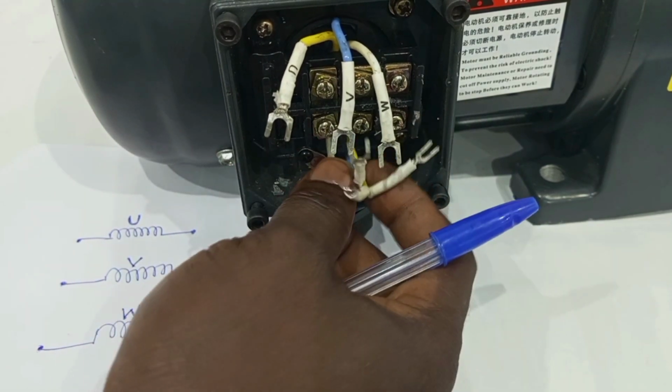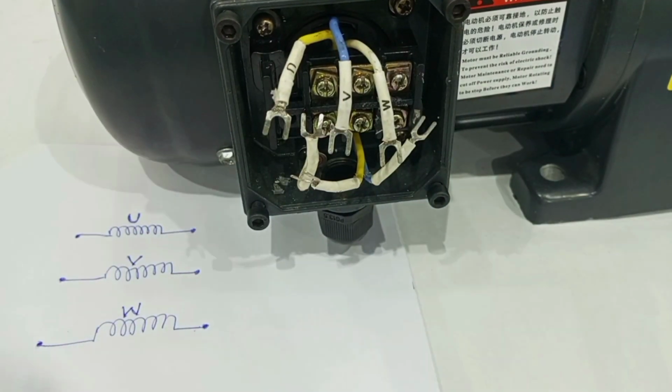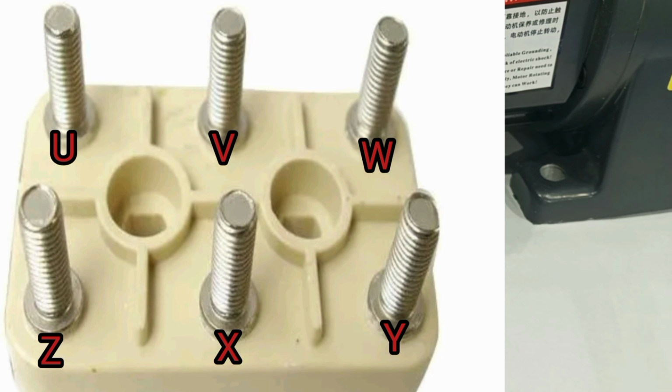Or you can take those at the down as the starting point, and those at the top as the finishing point. All right, so let's look at how the terminal block is labeled or marked, and then we continue to find out why it is so. So as you can see in this picture, this is a typical motor terminal block. And usually the terminals are labeled U, V, W at the top, and then Z, X, Y at the